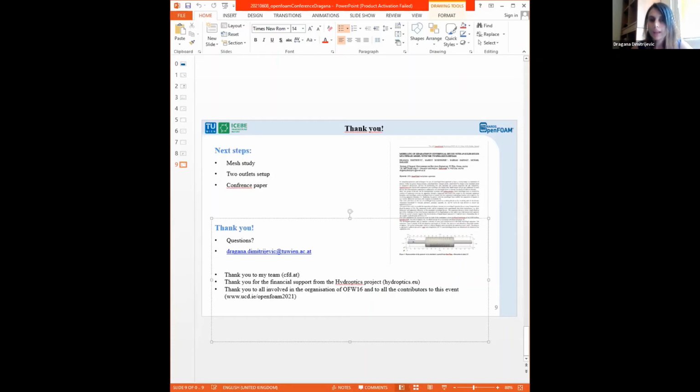In version 8, it is modified to multiphaseEulerFoam, which is an improvement of twoPhaseEulerFoam, and the mesh was done with snappyHexMesh. For the background mesh, I used blockMesh, and after that I used STL geometries to create the final mesh with snappyHexMesh.